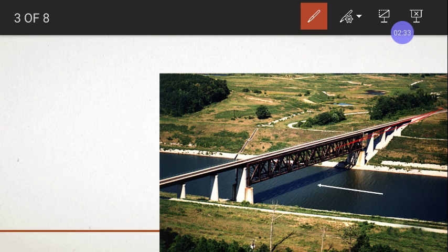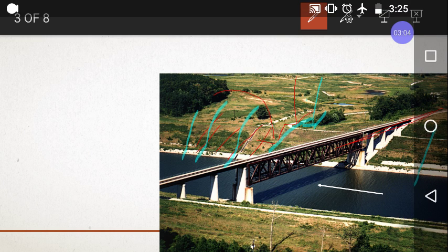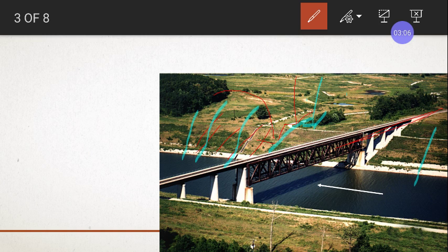And can you see this sloped embankment here? This part has some greenery over it. Small shrubs are planted, grasses are put over. Why is it done? Because during the rainy season, whatever water falls from this embankment slope comes into the channel on this side. So it should not carry soil with it, so we plant grasses over the sloped surfaces, right?